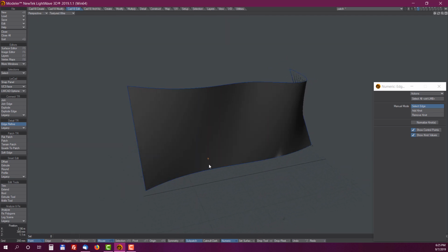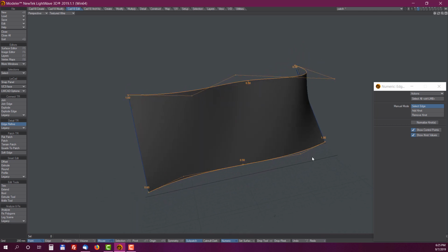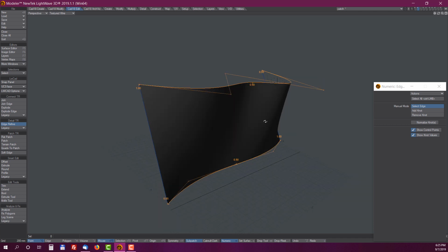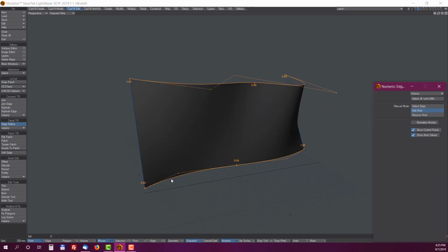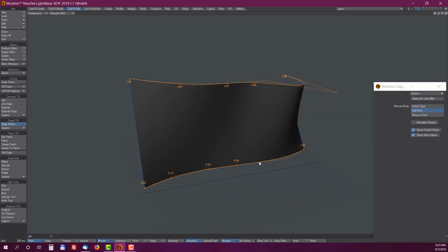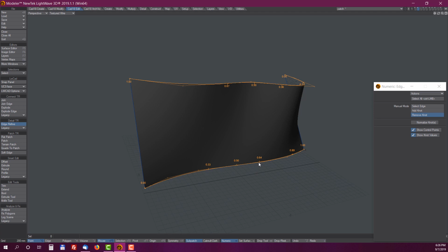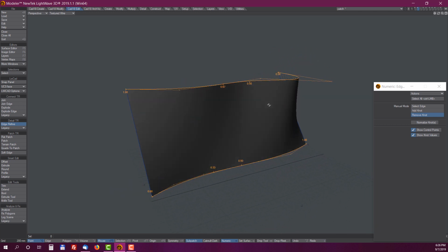So just select edge, and in case of surfaces, if you select one side of the edge, then the opposite side is automatically selected because that is how NURBS surfaces work. So now you can also refine a NURBS surface, and then you can remove these nodes. This is a fundamental operation of NURBS, and this will be advanced more with next versions.